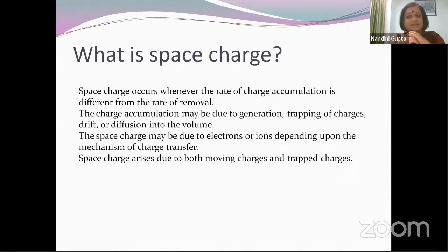If it exacerbates the field, it means that the dielectric material, under the application of a certain field, sees a higher electric stress in the presence of those space charges, whereas if the space charge was absent, the field would have been lower. The consequence is very easy to understand. Breakdown will be reached earlier. At lower fields, the material will tend to break down.